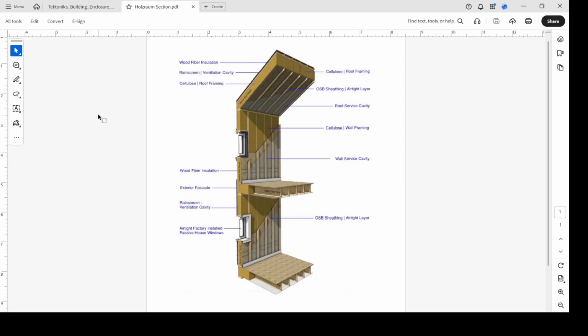So we're working towards something like this for the midterm. Multi-story, wood frame, lots of layers. This one doesn't have any kind of overhang. We'll talk about that a little more as we go. If you don't do an overhang, you really have to think really hard about keeping moisture out of the building and design it and install it properly. So I'll probably leave it up to you guys which one you want to model.